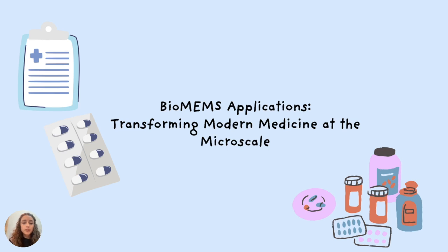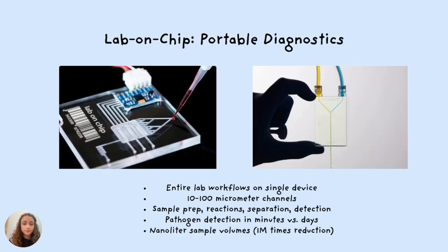Now I'm going to be discussing the applications of BioMEMS. One of the most clinically impactful uses is lab on chip, which is an entire laboratory workflow miniaturized on a single portable device. We're talking channels 10 to 100 micrometers wide, integrating sample prep, reaction, separation, and detection all in one place. The real game changer in this is speed.